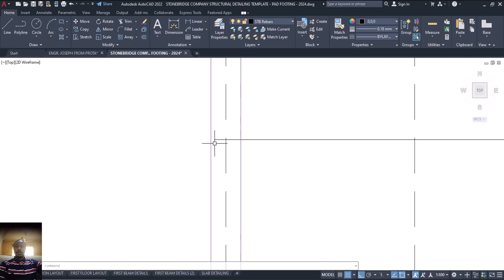Is 150. And since it's 150, then our cover bottom is what? 50, up 50, which makes what? Down 25 cover, up 25 cover. So if you now add 25 plus 25, give us what? 50. So therefore 150 minus 50 give us 100, which means our reinforcement this time around, our reinforcement up will be 100. Is that okay? This is 100.